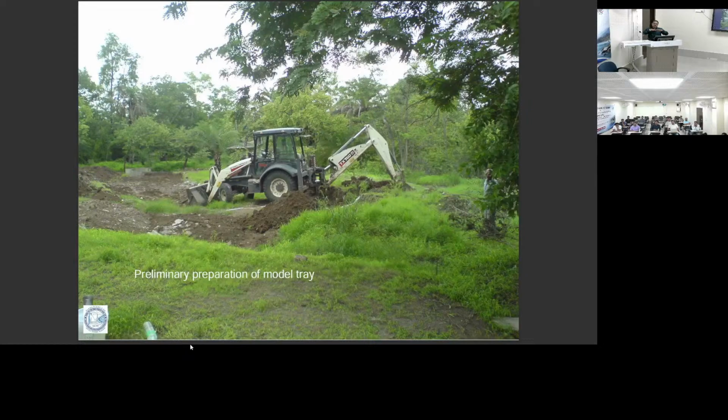From that, a minimum of 2 feet is best as far as possible. You go 2 feet below the deepest channel of the river in your model. In the bottom layer, you put a concrete, so that there should be no losses of water percolating into the ground. So you make a tray throughout the model, with 6 inch or 4 inch concrete. Then over it, 1 foot of murum, good quality murum.